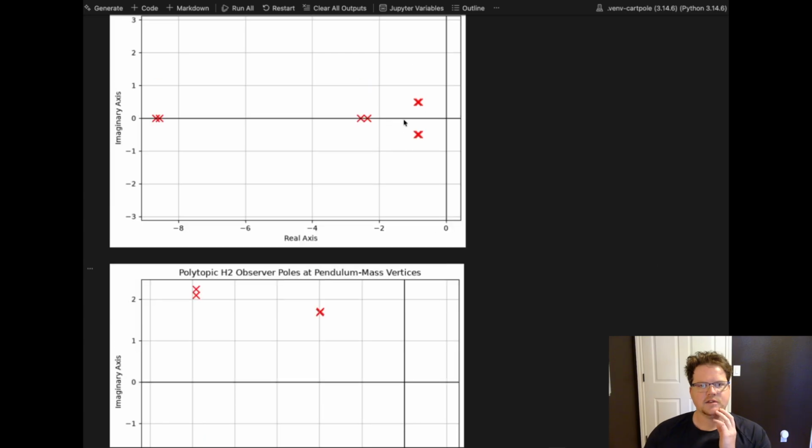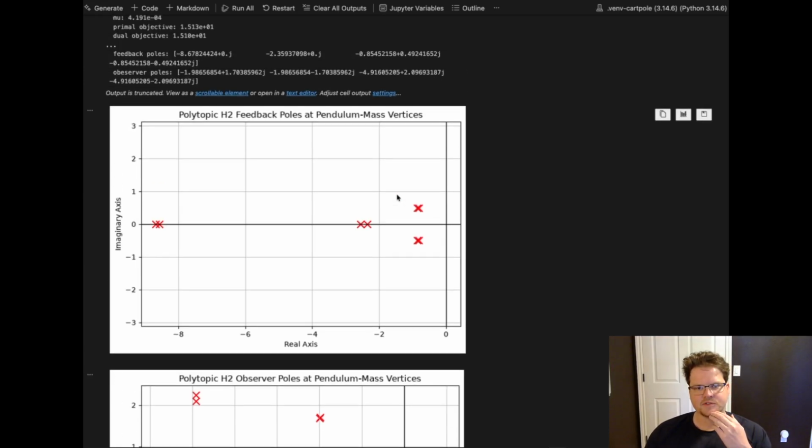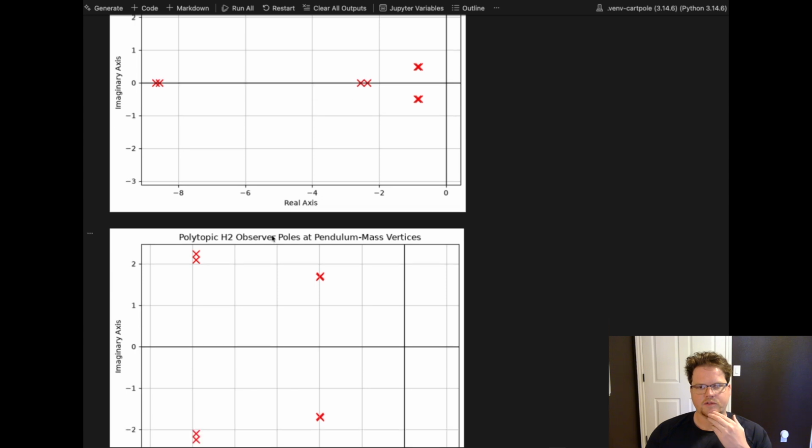All right, so we can see, interestingly, that we start getting more of this stacked pole coupling, which obviously is fine. It's on the left-hand plane, but the one thing is the transients, and I think what I was alluding to with the cart, if I were to vary that and then bump up the uncertainty, that's where we can hit a little bit more of these quasi-stable cases. These poles here get closer to the origin because it seemed like these are more with that slowish mode with the cart versus here's the pendulum up here. Anyways, just a thing that I noticed.